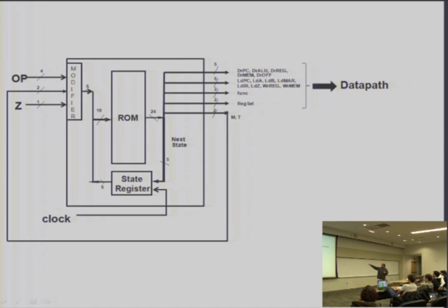When the modifier is all zeros, making sure that the top address bits are 0, then we're using 1/2 of the ROM. That's the normal unmodified, static portion of the ROM. Okay, and the dynamic portion of the ROM is when you have to make these micro branches, which happens at the end of the fetch macro state, or in the middle of the branch instruction, right? And during those conditions, some of these bits are not 0, which means some portion of the ROM we're going to use, but there's a large portion of the ROM that we're never going to use. So there's a space that we are wasting in the ROM when we do this.